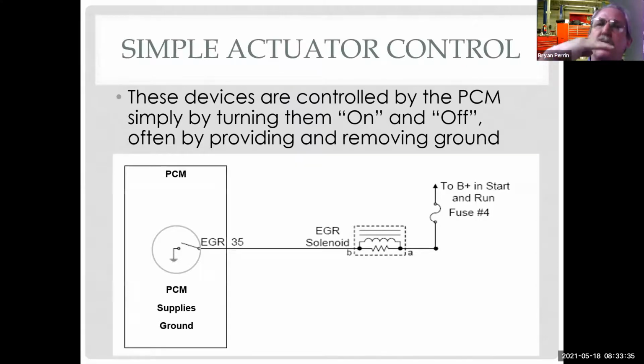So the only time it's turned on is when that wire between B and pin 35 is grounded, right? So this is my switched ground in the circuit right here. So I could test for that at pin 35, or I could test for it at B, couldn't I? Yes.